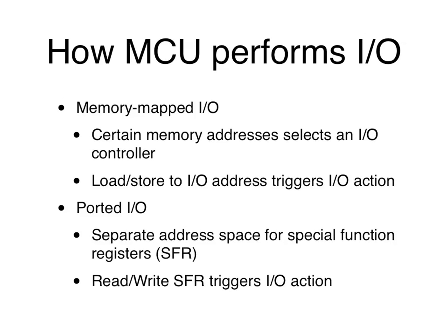Memory mapped I/O means you have a memory space, no matter how big it is. Space just means the range that you can address, because to access memory, you have to provide an address. Now, how big is that space? Well, it's 2 to the power of the number of bits. So if your address is 16 bits long, how big is the memory space?